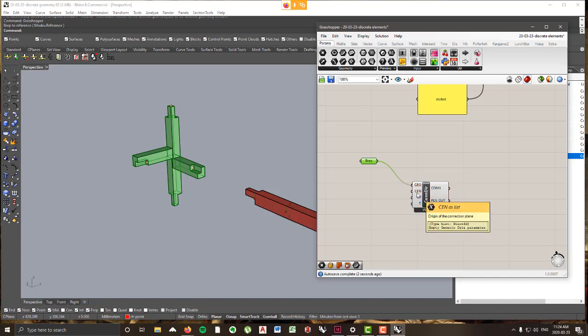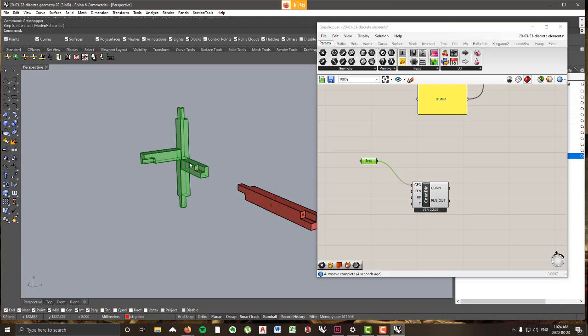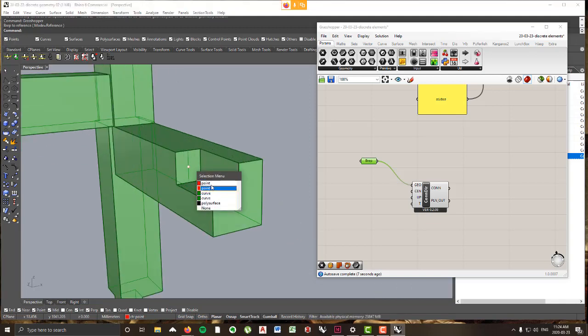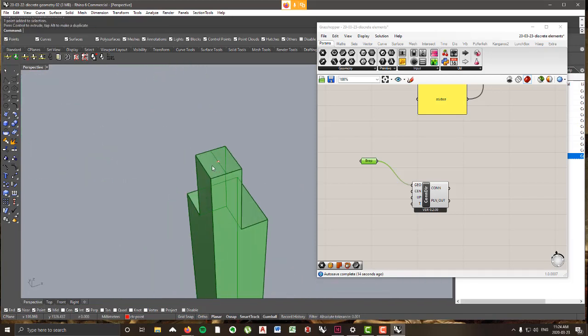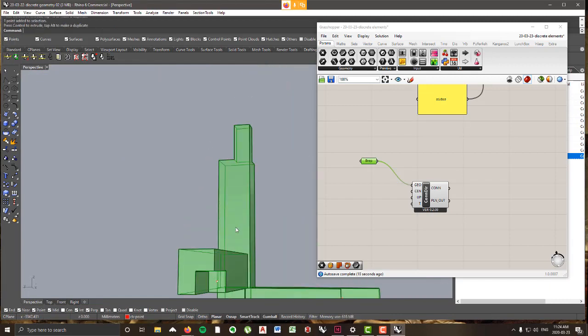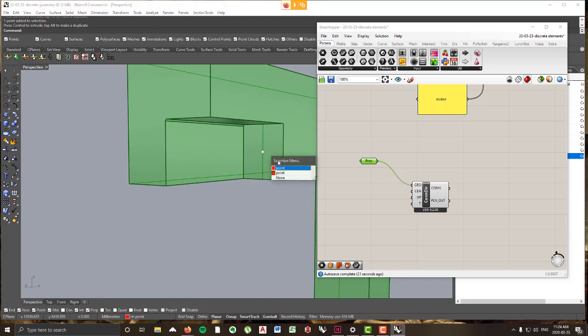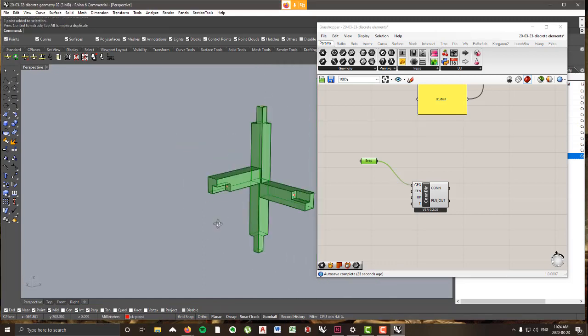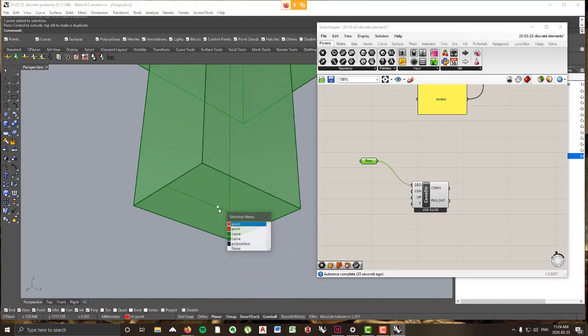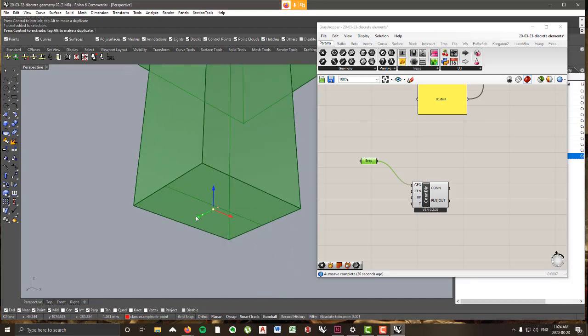The center points is going to be all the center points of the object. And again, since we have double points here, before we select all these points, what we want to do is select one of the two points on each of these connection sides and shift it over slightly. That's going to allow us to easily select them in Grasshopper. Otherwise, sometimes you might not select a point, and then it'll cause WASP to throw an error. So we're avoiding that in advance by slightly moving over those points. And we'll move them back again, of course.